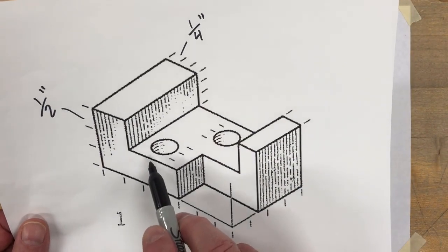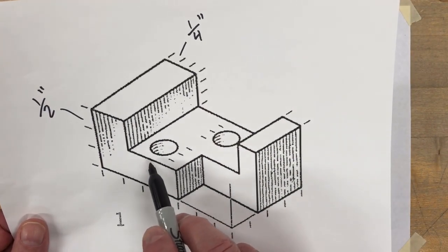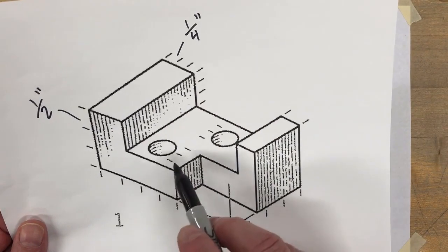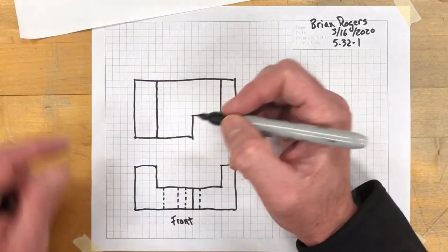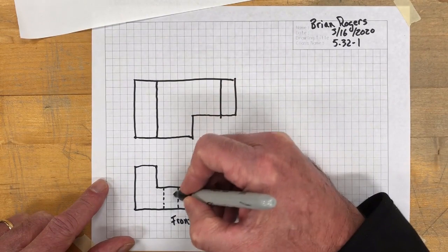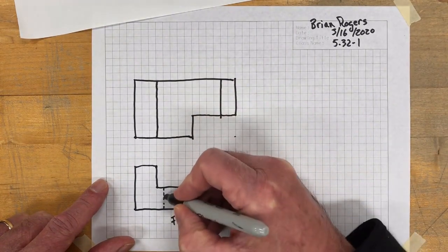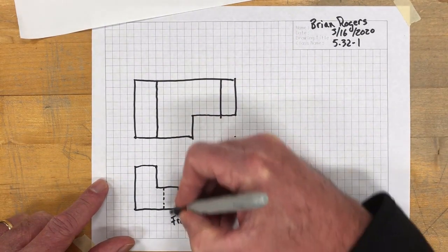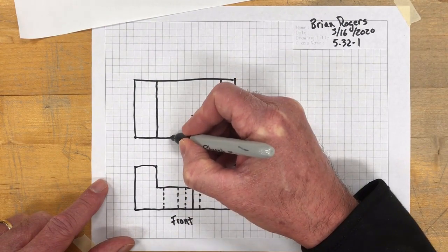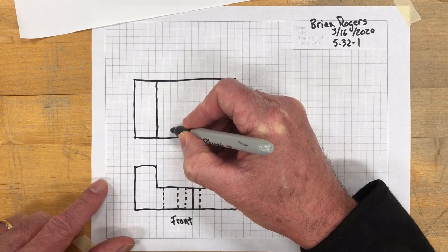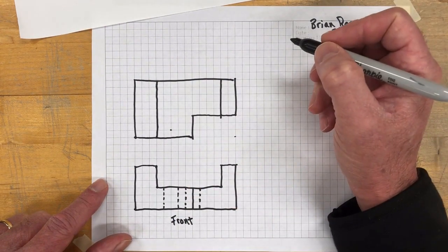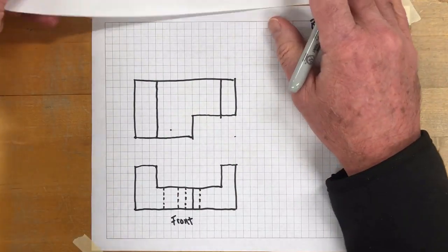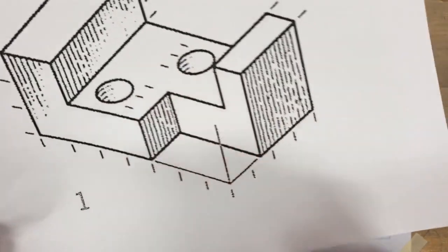So as I said, the front hole, or the leftmost hole, is 1/4 inch back, and it's 1/2 inch in diameter. So here's how I handle this. I take this center line here because it's exactly in between these two hidden lines. I project that up, and I measure back from front to back 1/4 of an inch, just like we see illustrated right here on the drawing.